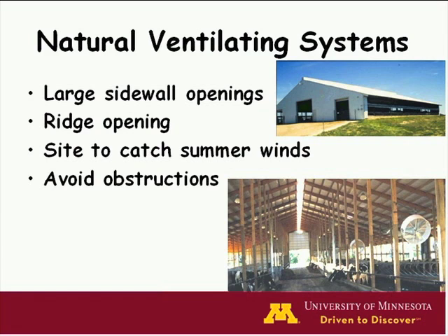Okay, natural ventilation. Again, the driving force is wind and buoyancy, and so we have large sidewall openings that can be closed up in the wintertime to provide a windbreak, and in the summertime they catch the summer winds, and we have an open ridge so we can have air blowing in one side and out the other, and some going out of the ridge.